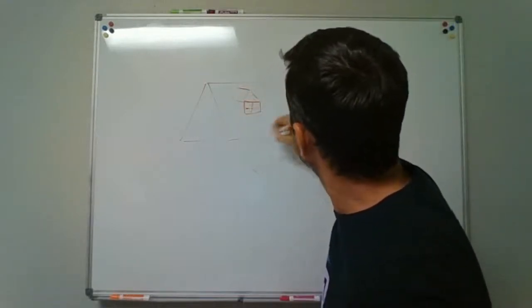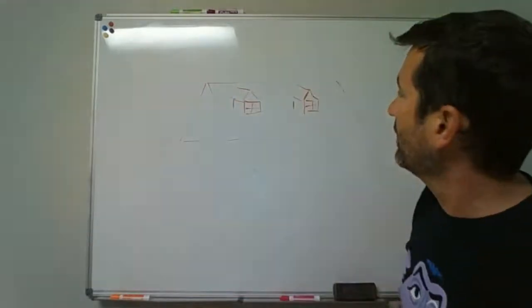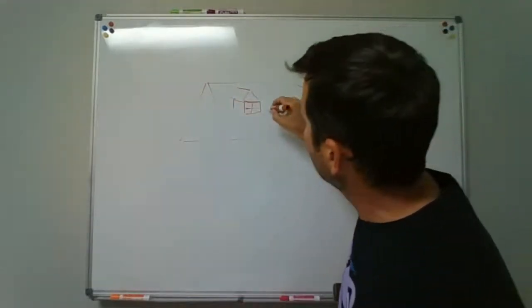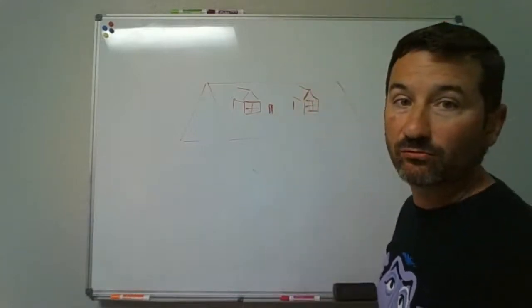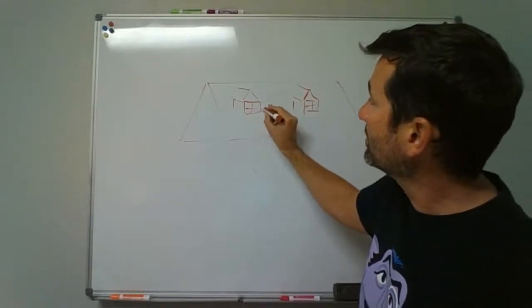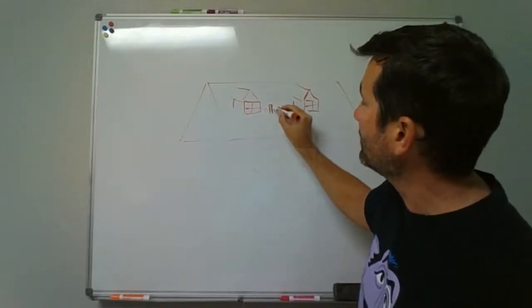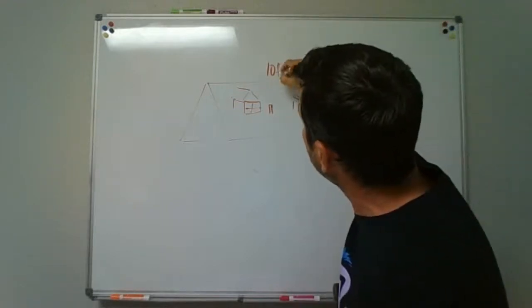So you got dormer windows up on top of here. Maybe in the upstairs, you're going to have a vent coming up. And maybe that vent's going to come up through the roof right here. If it is, you need to look to say from the edge of this window, this vent has to be at least 10 foot away.